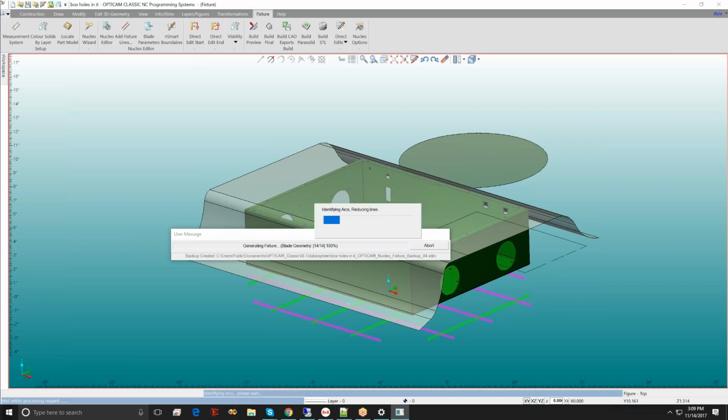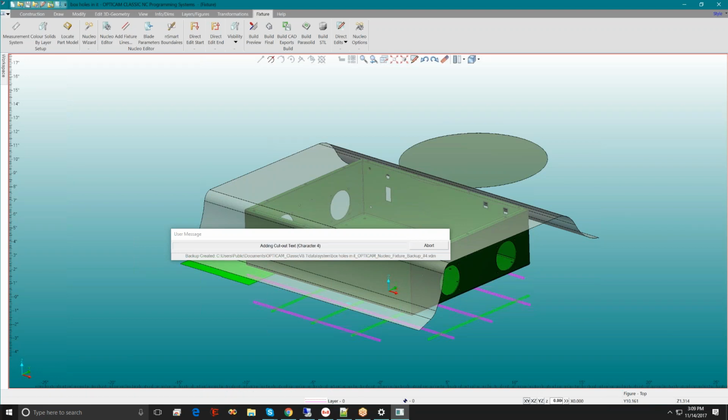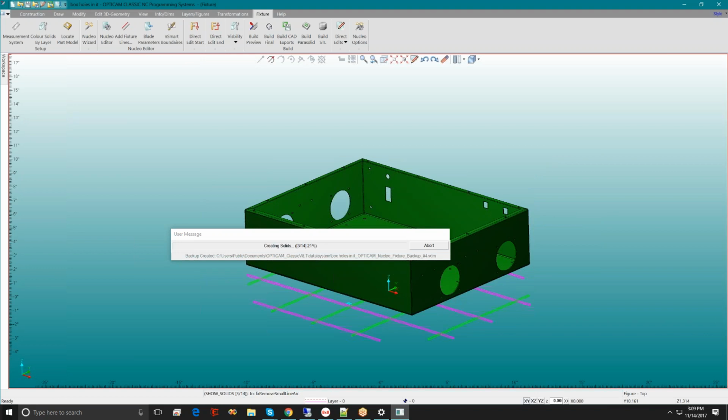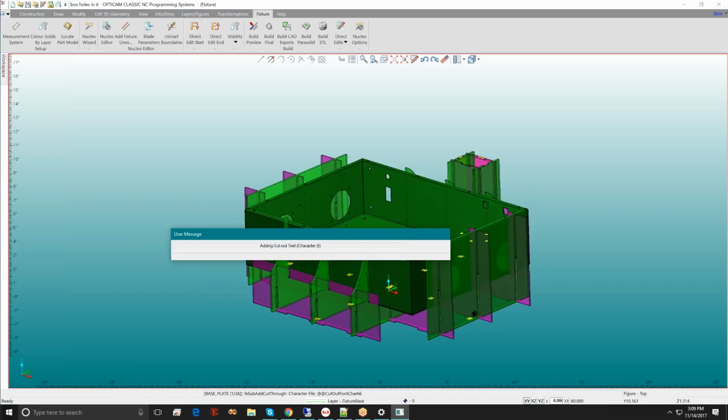If you want to follow the general shape of the thick part, say it was some kind of grabber that you see in a scrapyard, you might want to make it follow the curvature of the hook on the end of it, really. So it's almost finished. You see, it's made it like that shape now. All right. That could come in handy someday. I just want to make you aware of it. If you wanted to form it to a given shape, you just draw a boundary. You can do it in your other CAD system before you bring it in, but you can do it here too.